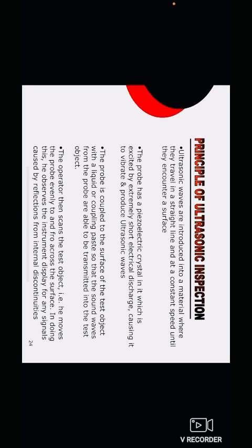Principles of ultrasonic inspection. Ultrasonic waves are introduced into a material where they travel in a straight line and at a constant speed until they encounter a surface. The probe has a piezoelectric crystal in it which is excited by an extremely short electrical discharge, causing it to vibrate and produce ultrasonic waves. The probe is coupled to the surface of the test object with a liquid or coupling paste so that the sound waves from the probe can be transmitted into the test object.